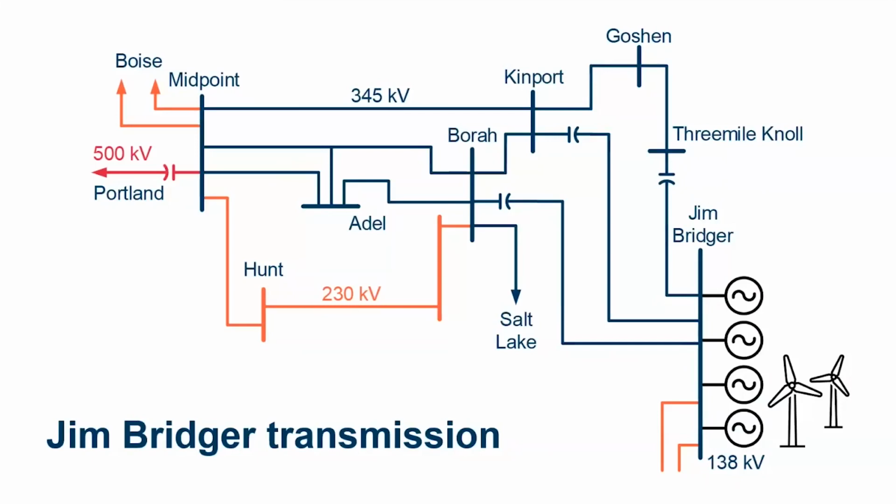Each RAS system consists of 3 identical controllers gathering IOs, performing 2 out of 3 voting on the data, and performing calculations to decide if an action is necessary. The total round-trip time from input assertion to output contact is in milliseconds or at sub-cycle speed. An action, for example, generator trip or capacitor insert bypass, cannot be executed unless 2 of the 3 systems agree in a triple modular redundant RAS.